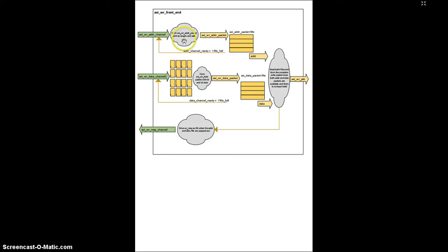you have to save the address and incoming write data into two separate FIFOs, as we have two channels in the write packet, where there is an address channel and a data channel. But in the read portion, this interconnect will be getting only the read address, which it needs to route to the OCP client. Thus, in the read front-end module, you will only have this portion where it stores the read address, and it will not have the complex write data storage part.